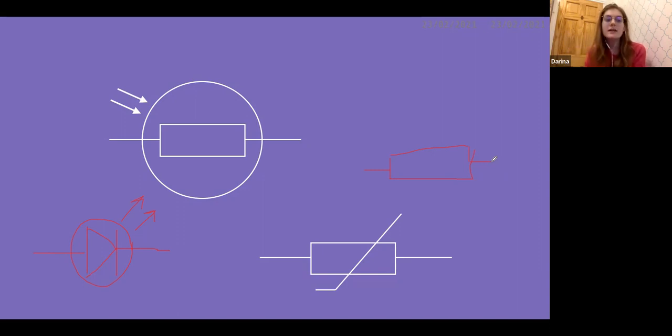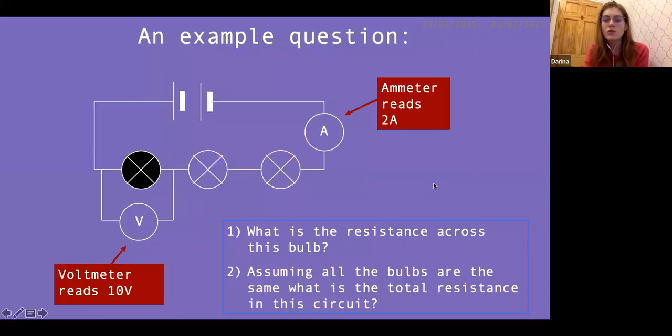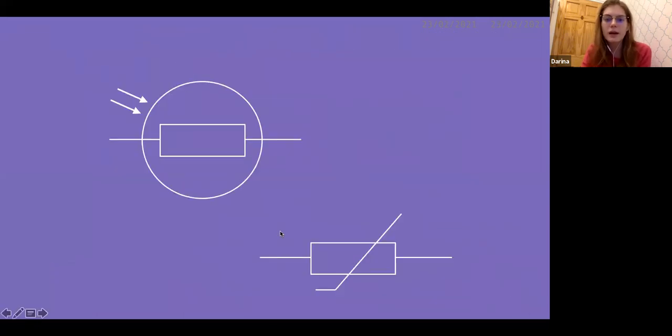So we've got a couple of ideas here. We've got a fuse? Not quite a fuse. A fuse would just be with a line straight through it. So that's not correct. Any other ideas for what any of these are? So they're resistors now, we know. And we've already had a chat about why it's not an LED, it's not a fuse. Ooh, don't worry about transistors. Transistors don't come up on your GCSE spec. And we've got an idea of a variable resistor. So again, remember variable resistors, they have an arrow drawn through them. That's the vary. Okay, I can tell that no one can quite remember.